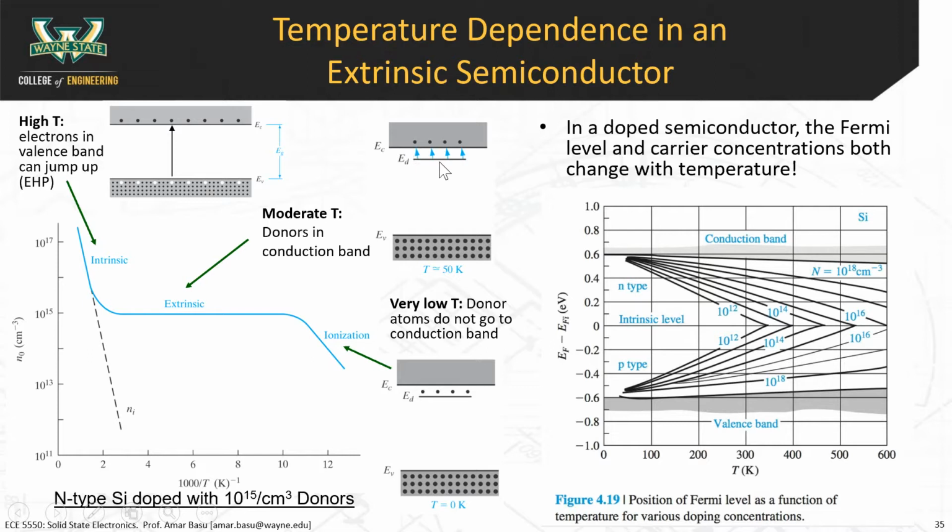So there's enough energy for small energy transitions like this to happen. You don't want the system to be at such a high temperature where this energy transition can happen, the one going across the band gap. Because if that happens, then electrons in the valence band are going to jump up into the conduction band, and now your entire material becomes conductive everywhere.